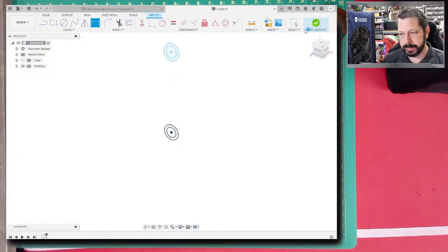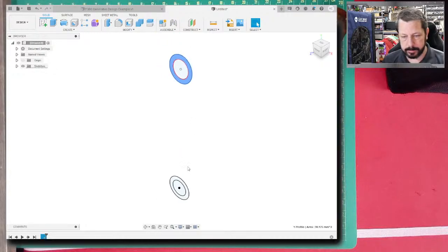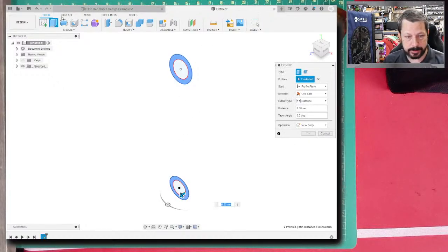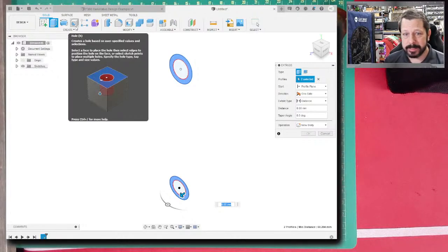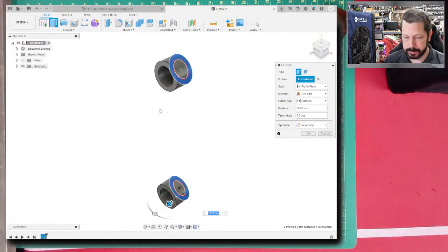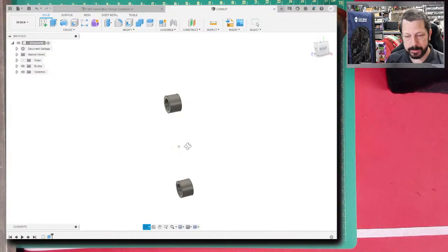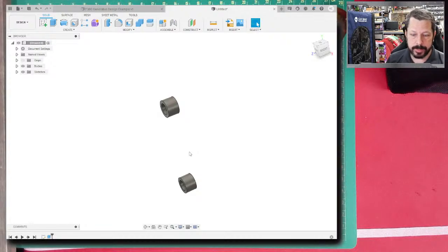Okay, finished sketch. It shows all of these, and you click on the area. I hold down Control to click two areas at the same time. E button extrudes, and there's all kinds of buttons. For most of these software, if you know the keyboard shortcuts, you can be much faster than trying to find all the buttons in the menus everywhere. So I just extruded these 10 millimeters. Those are going to be our bolt holes and bosses around the bolt holes that we want to preserve. We'll create some kind of fixture when we go to our simulation, so that these are preserved regions that are fixed in space.